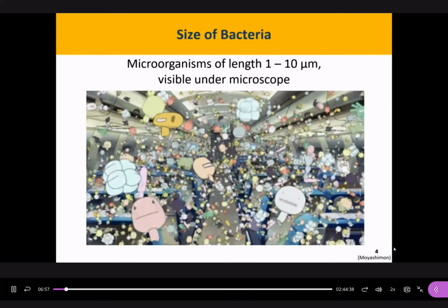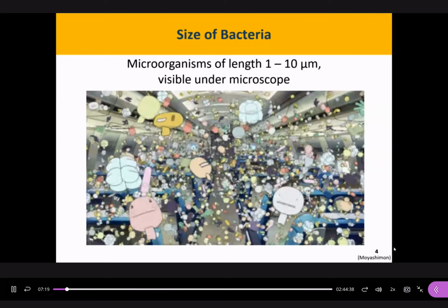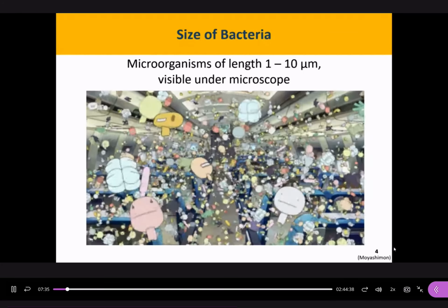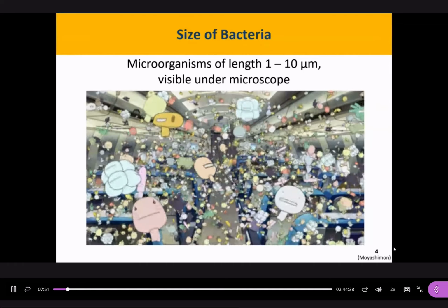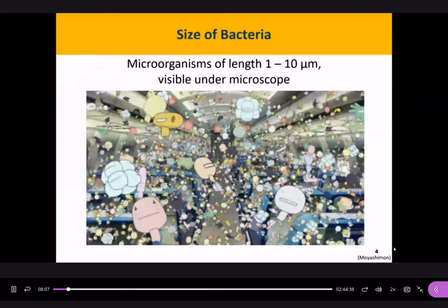Microorganisms are everywhere: in the coffee you drink, in the air we breathe, in the water we drink. It's a matter of concentration and of different types, but it's abundant. The number of bacteria, or more broadly microorganisms, is much larger than the human population on Earth. Its typical size is 1 to 10 micrometer. So based on the size, what method can we use to remove them from water? Can we use sedimentation? Probably difficult without coagulation, unless you use some coagulant. What else? Can we use filtration? Yes, we can use filtration based on size.